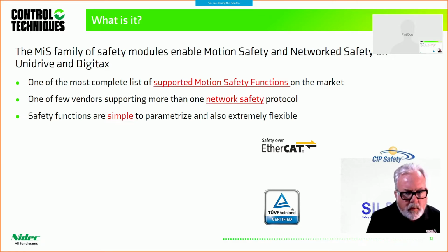This module supports FSoE, which is Functional Safety over EtherCAT, and it also supports CIP Safety, which is the Rockwell/Allen-Bradley safety standard, or safety protocol, I should say.